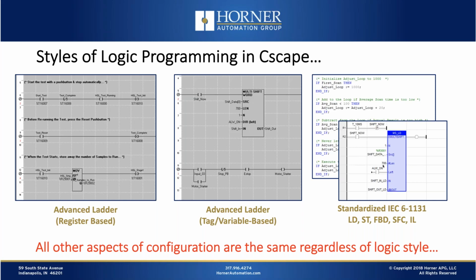Although, frankly, the ladder that's included with the standardized IEC 61131 isn't quite as flexible as advanced ladder. So those of you who are primarily ladder programmers, you would probably prefer tag-based ladder as opposed to the IEC. But there's a lot of enhancements coming to IEC as well. So for that group, or for those who aren't sure yet what languages you want to use, that'll be something you'll want to evaluate.